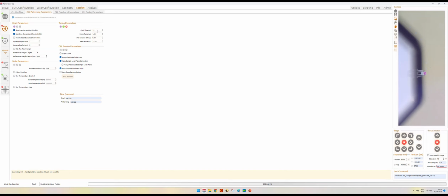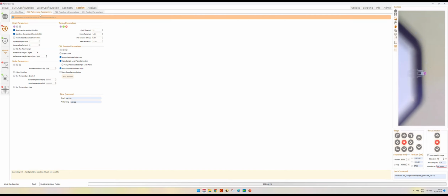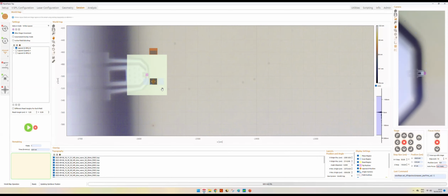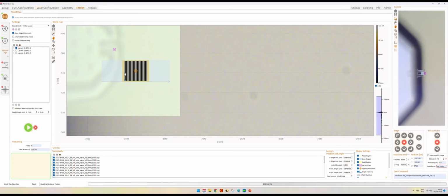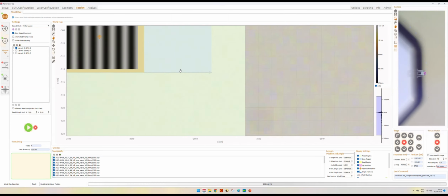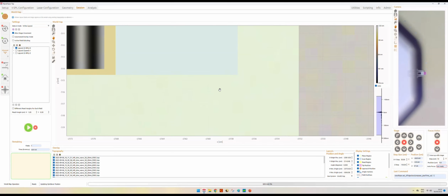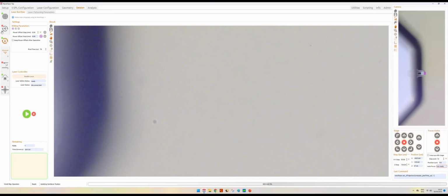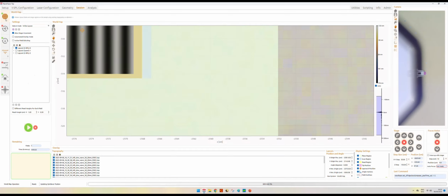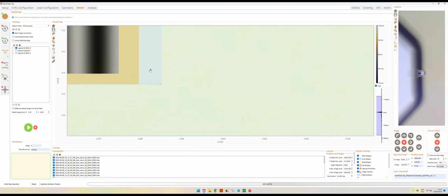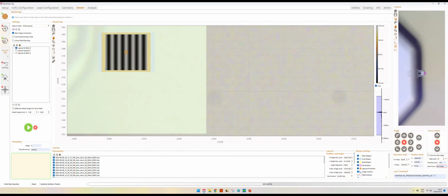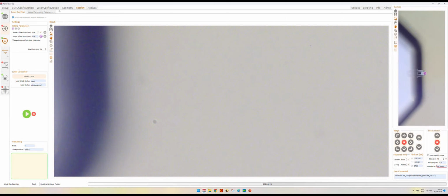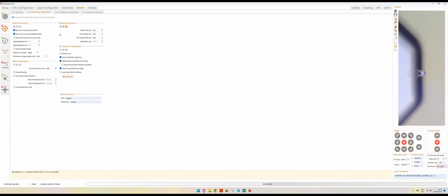because when we increase or decrease the patterning speed, we also change the dimension of the scan. It can sometimes be too large to fit in the piezo range. We see now that we have an extension of around 10 microns, and if we put this back to 150, for example, we'll see that we have an extension of less than 2 microns. So it's a parameter that's nice to know and nice to play around with.